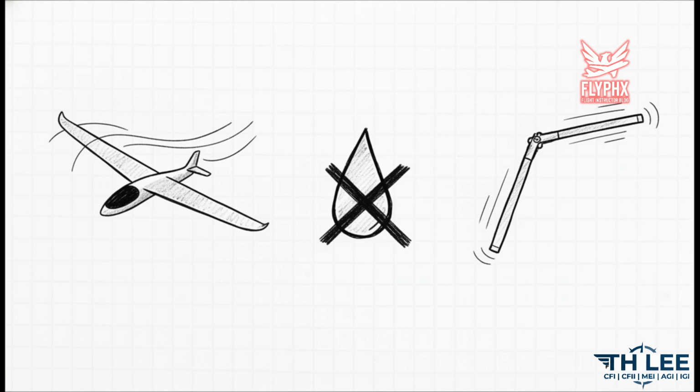Third, composites offer far superior performance in a flexing environment. They do not suffer from metal fatigue and crack growth like metals do, which gives things like helicopter composite rotor blades and hubs considerably higher design lives.